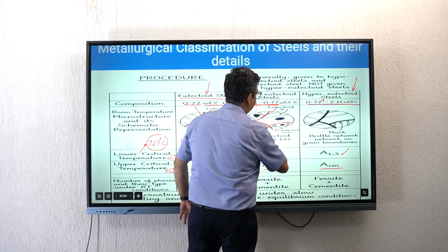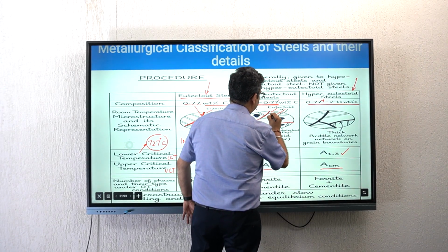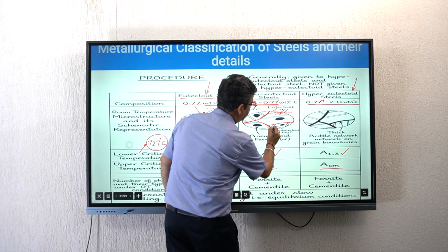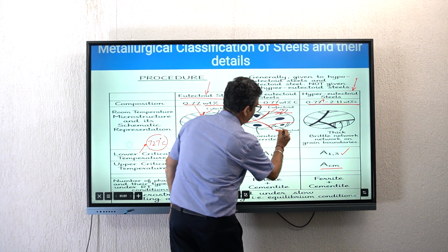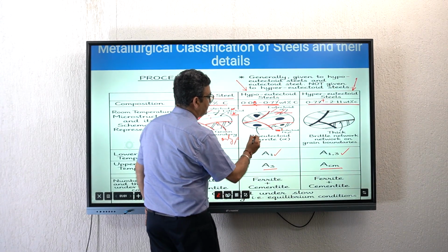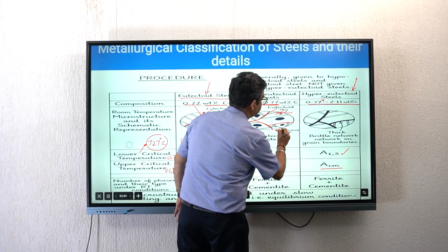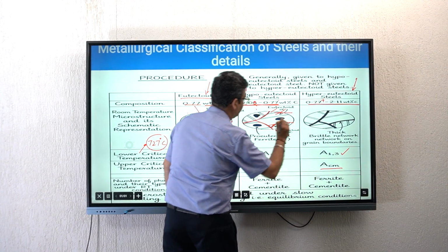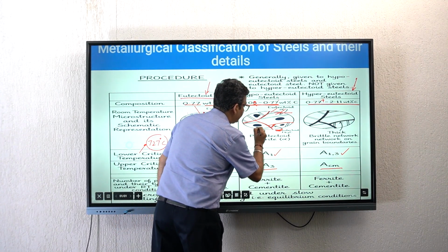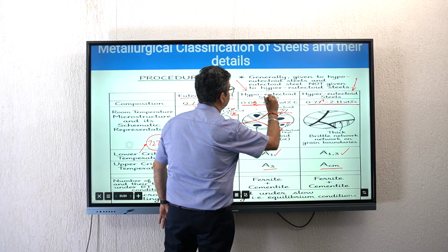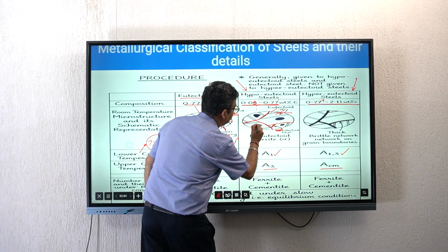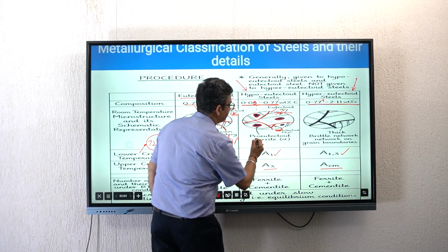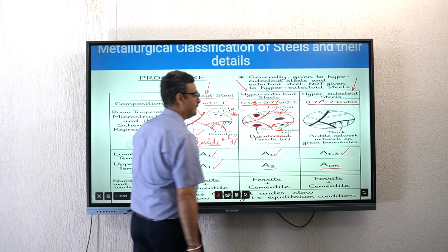This again is eutectoid ferrite. Thinner lamella is eutectoid cementite, so this thinner lamella should be called eutectoid cementite. And this pro-eutectoid constituent in the case of hypoeutectoid steels is ferrite. This ferrite that is sitting within the grains in the form of lumps is pro-eutectoid ferrite.